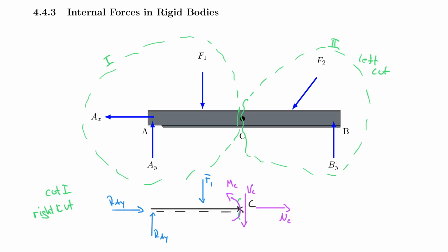So mathematically, you already have all the tools in place. You just need to understand how to apply it. So you know mathematically what to do. We just need to find out how we do it. But I think I already gave you a first insight. You cut at the location where you try to find your internal forces. You redraw your free body diagram. You are missing forces that can keep it in balance. Then you add the forces.